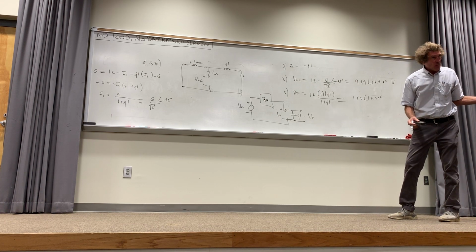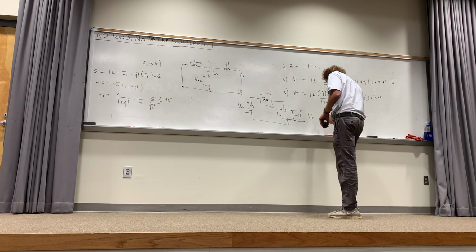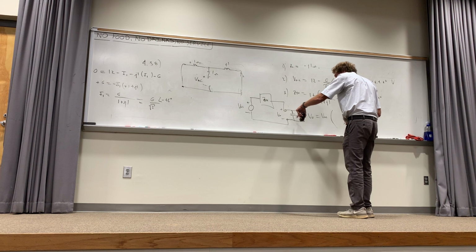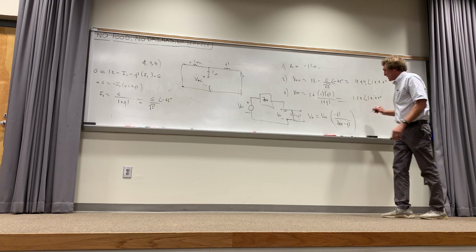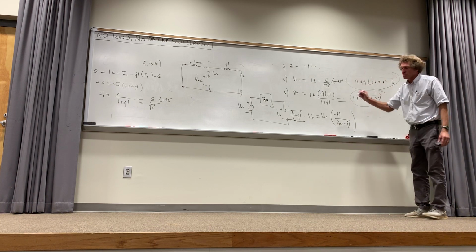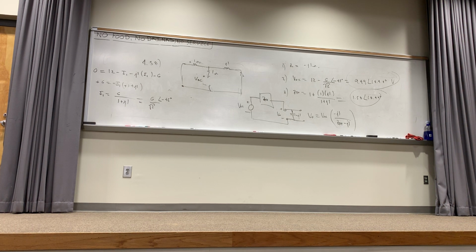Now to get the output voltage, I do voltage division. So my output voltage here is going to be equal to V open circuit times minus J1 over Z Thevenin plus minus J1. Now I left it that way. Here is Z Thevenin, here is VOC. You can punch it into your calculators. Get used to doing this.